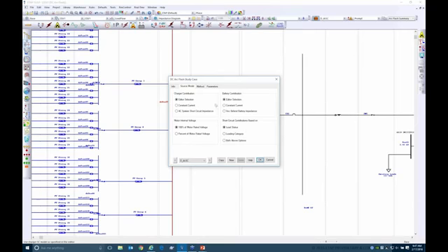Select the short circuit model for various sources such as batteries, rectifiers, motors, inverters, and so on. Select from different arc flash methodologies, and ETAP's actually the only program right now that supports 3 different methods based on the complexity of the system for doing arc flash calculations, such as maximum power, Stokes and Oppenlander.